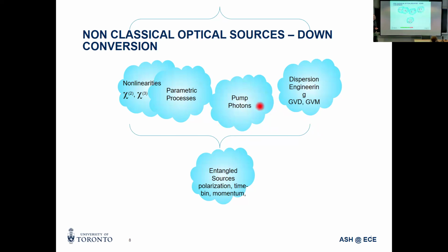And then we can also do all this. It actually requires dispersion engineering using different materials, tuning the width and thicknesses of your waveguides and all your on-chip nanophotonic components through critical tailoring to get your phase matching and your index matching, so you can access all sorts of different modes and have high tunability in your nonlinear portions of this to generate entangled sources and squeezed sources.